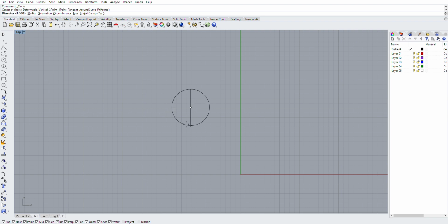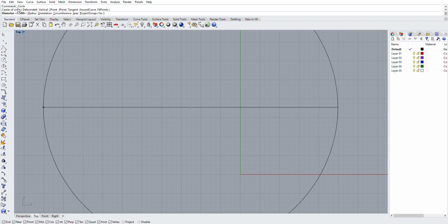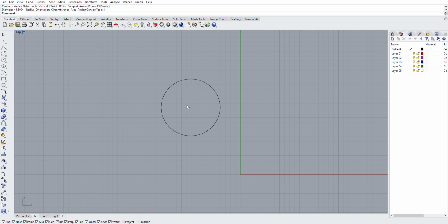So let's try something a little bit different here. How about a 3-bolt exhaust flange, say like a header flange. Start with a 2.5 inch circle here. And our bolt holes are going to be 3/8 bolt holes, 0.375. Knowing fractions over to decimals is handy because we all work in SAE up here.